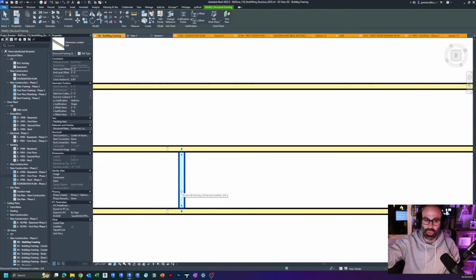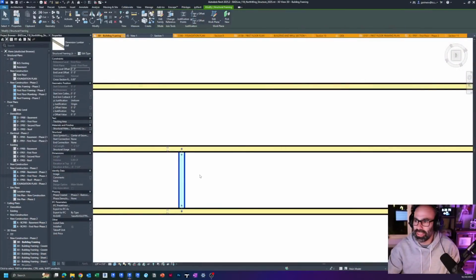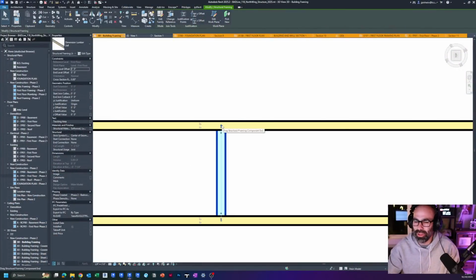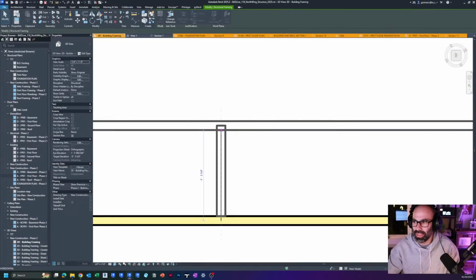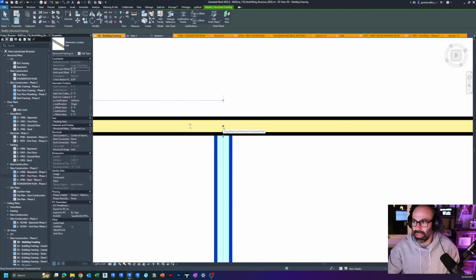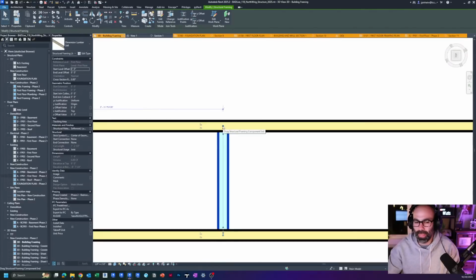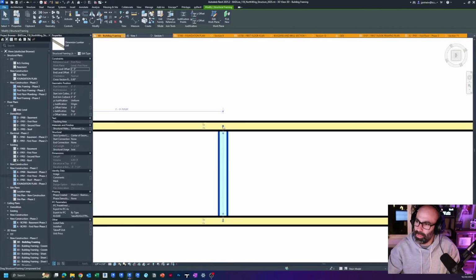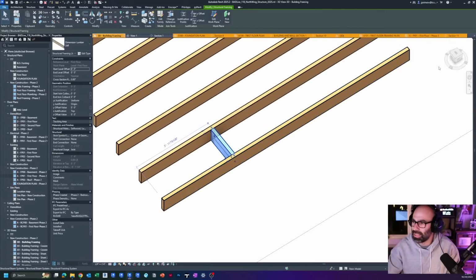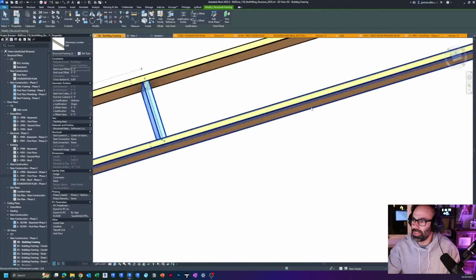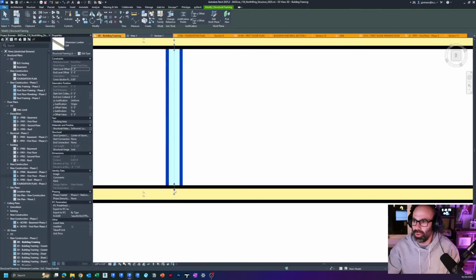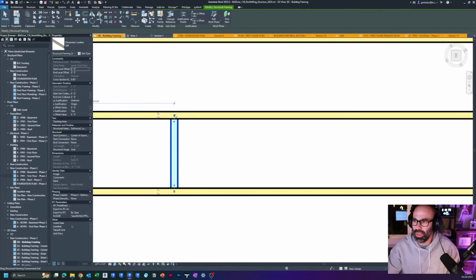One thing that I will say though, for anyone who's just maybe starting and getting used to using beams in Revit, a nice little tip I'll give you guys is whatever you do, try your best to utilize the blue dot for dragging your beams. This might burn you here and there because it's locking to things, and so sometimes it'll get off skew. But I promise you, the second that you start messing with the arrow to do something, and I'll show you exactly why.